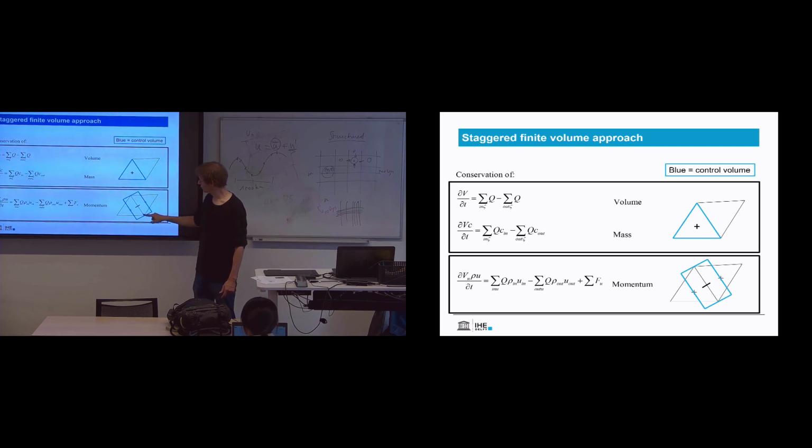So basically what we do is we calculate contributions to the velocity here, then we do some interpolation to the cell centers, and then we calculate the average of these two adjacent cells. It's a somewhat more difficult way, but you need a different control volume to do that. And then we divide everything by the area of this, and then we get a finite volume closed out.